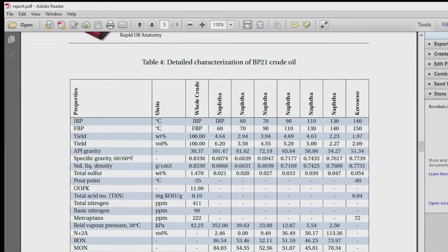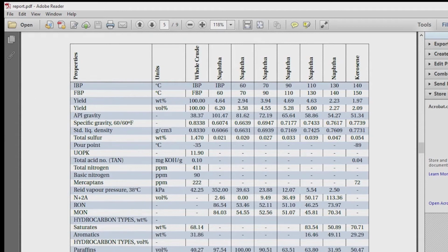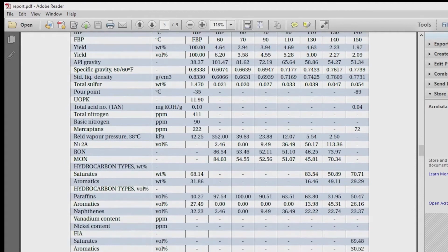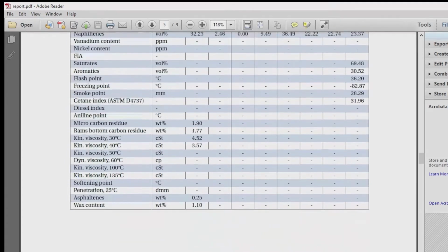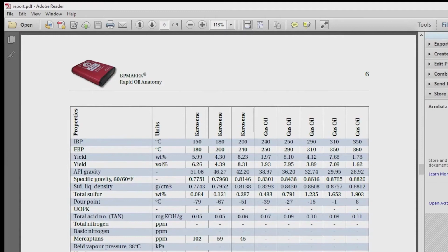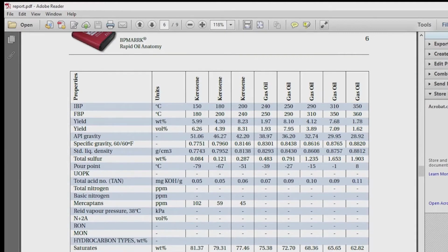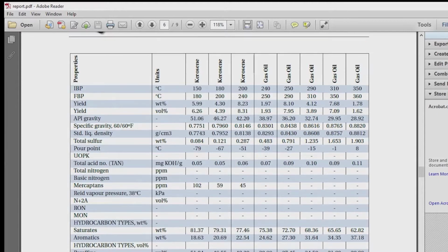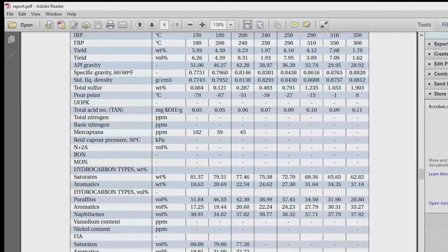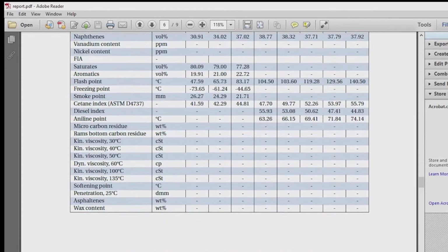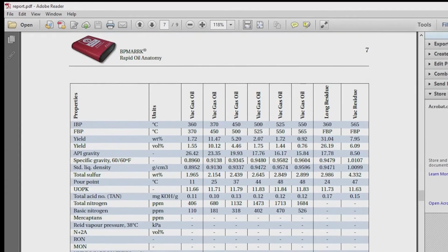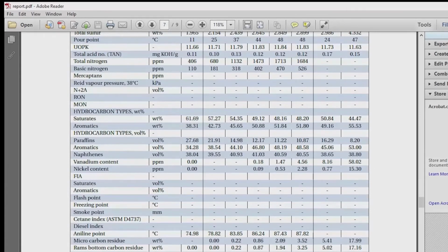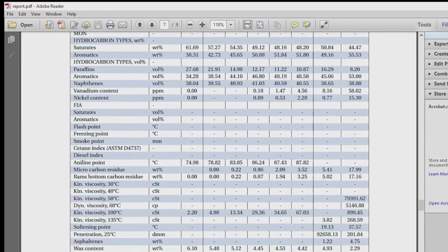For instance, for naphtha, which is one of its cuts, it can provide 6 different cut fractions, and you can select and know much detailed information about each cut by looking into the properties. It has important properties like octane number and can be useful for naphtha or even cut-wise information to composition details. Pour point temperature, which could be important for kerosene and even the paraffin, naphthene content or metals and so on. It gives a whole gamut of information for entire assay, starting from light gases to the heaviest fraction in the crude.